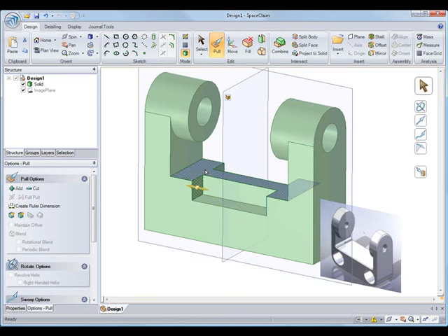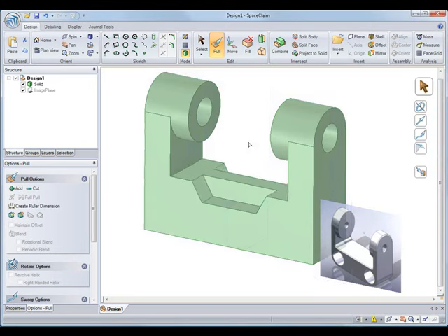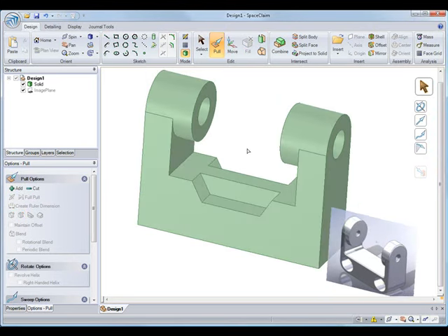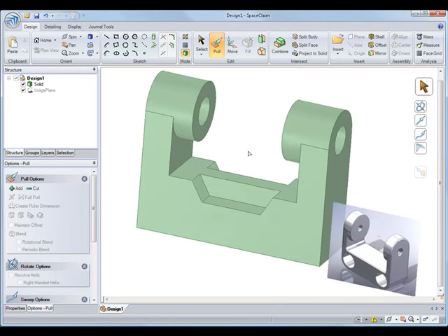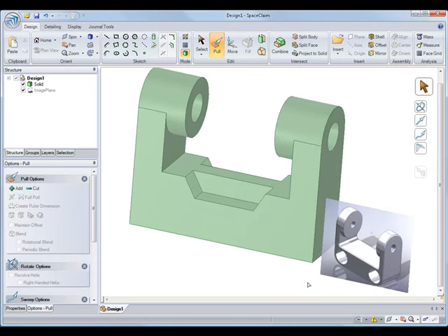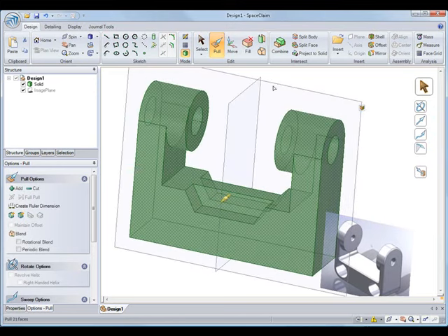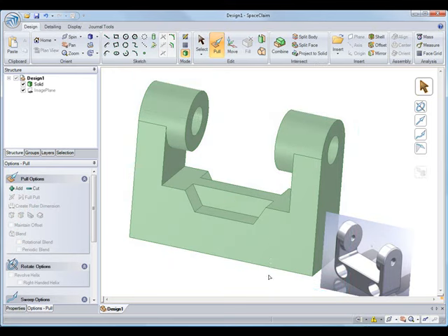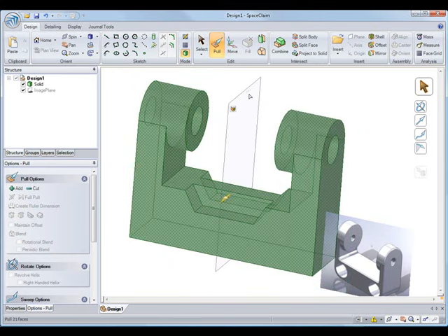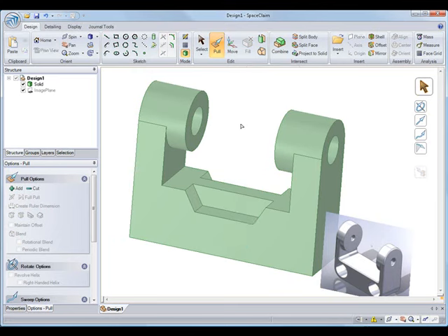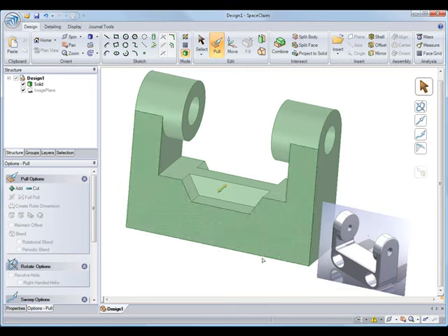So once I'm done making any changes that I really want to hold symmetric, I'm actually going to get rid of these mirror planes, just because I only want them temporarily. So a good way to delete the mirror planes on your model is to select the entire model, which will show you all of the mirror associations that are there. So you see I have two, and I'll select one and delete it with the delete key. And I'll go back, select the entire model, select the plane, and delete it. So now our solid is not obeyed by any mirror associations.